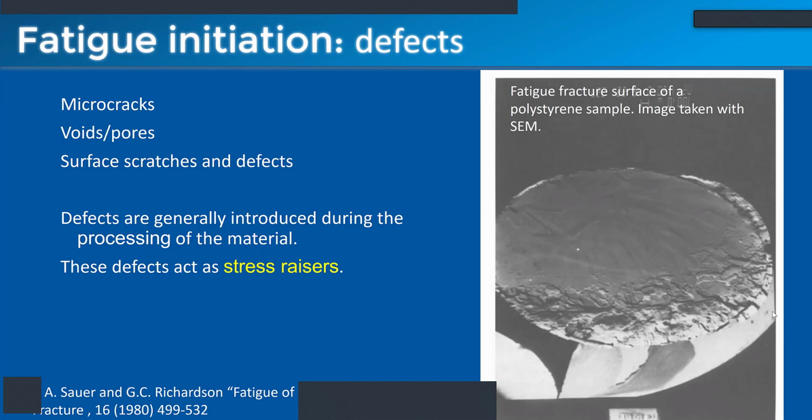Okay, so this slide here is just showing how different types of shapes or different types of defects or cracks in your material will give different stress distributions. For instance, if you have a hole in your material, the stress felt around the area of this hole can be up to 3 times as high as the stress that you're applying to the rest of the material. So a hole is concentrating the stress. The stress around a crack, like we drew before, can be up to 8 times higher than the stress that you're applying to the bulk material.